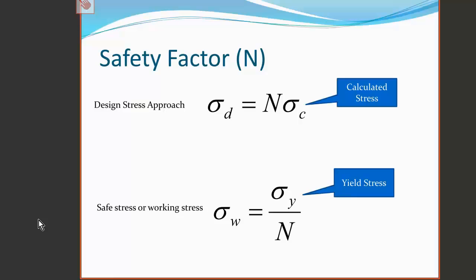Sometimes in the textbooks it is explained that a safety factor is actually an ignorance factor, to account for the fact that there are some unknowns associated with their application. For instance, wood is a natural material, and there is wide variability between the strengths of pieces of wood, even from the same tree.